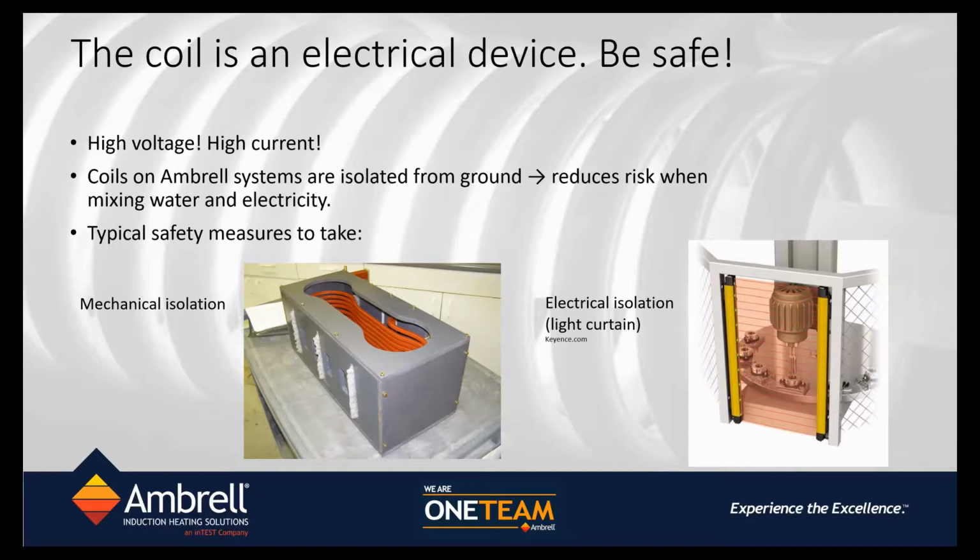The big advantage with induction is as soon as that signal is interrupted or that circuit is interrupted, the induction heating power goes off instantly. It does not, however, cool the part instantly, so you might still be at risk touching a hot part or getting near a hot part. So needless to say, safety is of utmost importance when working around induction heating systems.